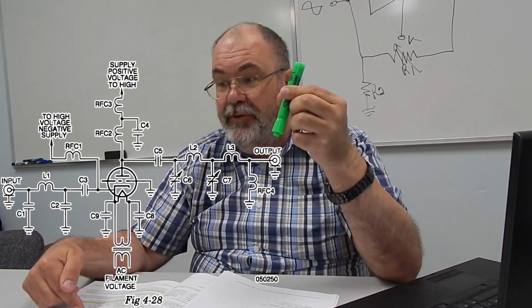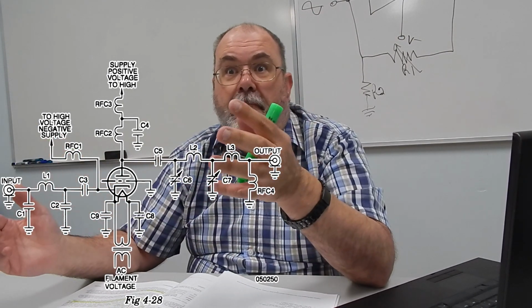And once again, this comes back to common mode rejection. We talked about common mode rejection with our op amps. Well, this is a transformer. Believe it or not, transformers have really good common mode rejection. Any signals that are induced on those two wires that are in phase with each other are going to simply cancel out in the wire.